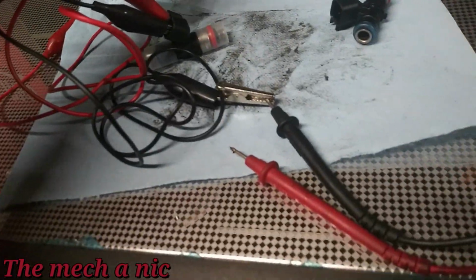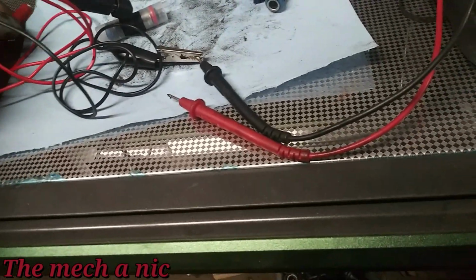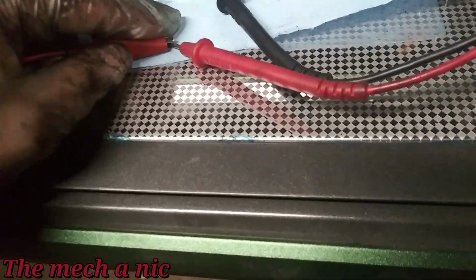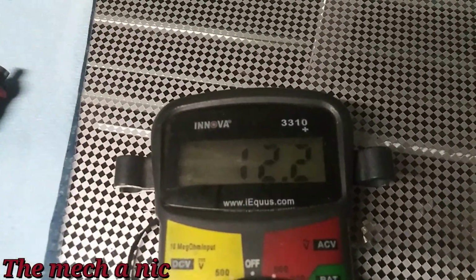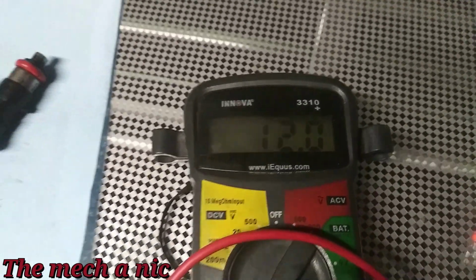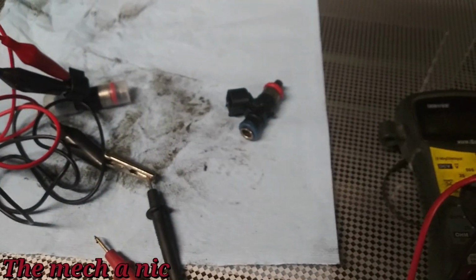Okay, so here's the new fuel injector, and I've already got my leads connected to it. All I have to do is touch the red one to the red one. I can't clamp it on because this clamp is broken, but you can see on the new one we got about 12.1 ohms.